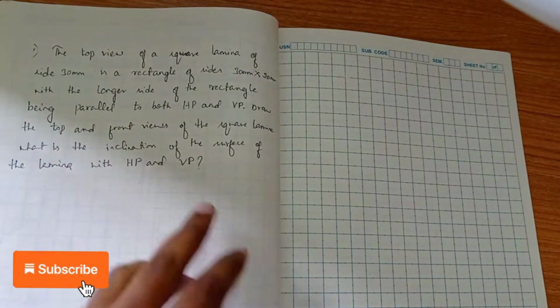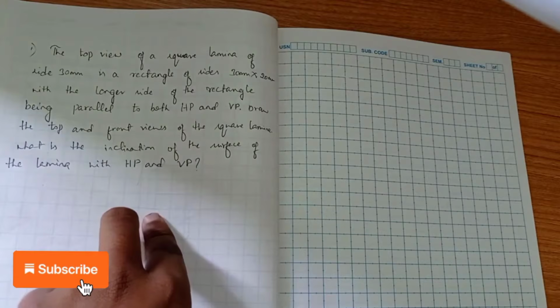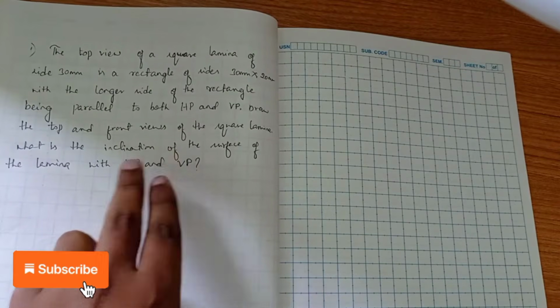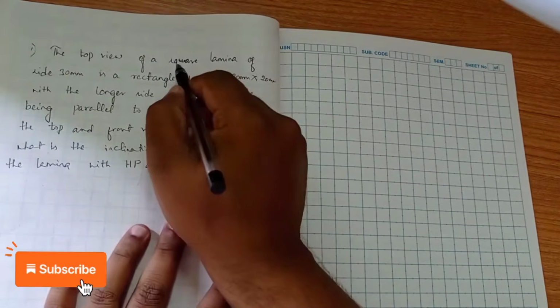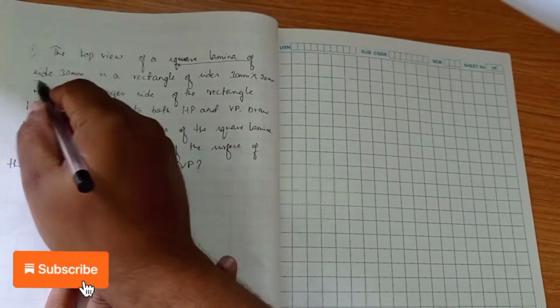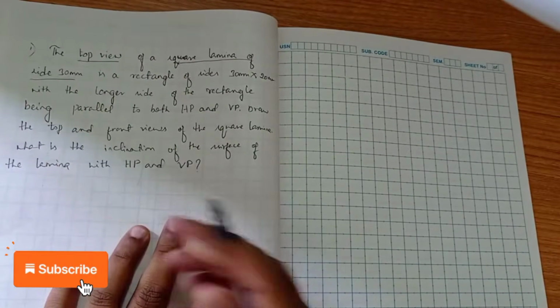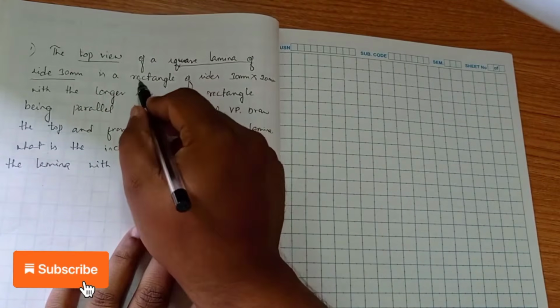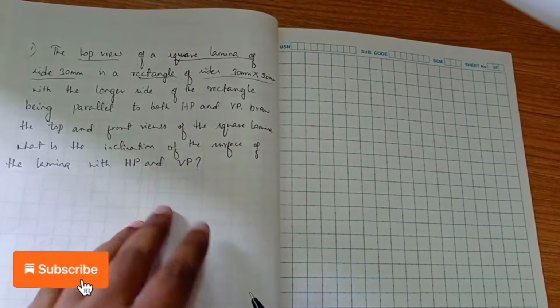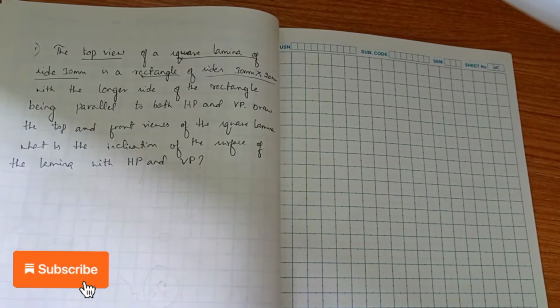You can see in this problem they have not mentioned any kind of inclinations. Okay, there is no inclination to HP or VP. So based on the question given, we have to do it. First thing is we have to construct a square lamina of dimension 30. This is the top view. So top view of a square lamina means the first projection will be a square, second will be a rectangle of side 30 into 20. Instead of giving an angle, they mentioned the views here. Okay, first I will proceed with the question here.